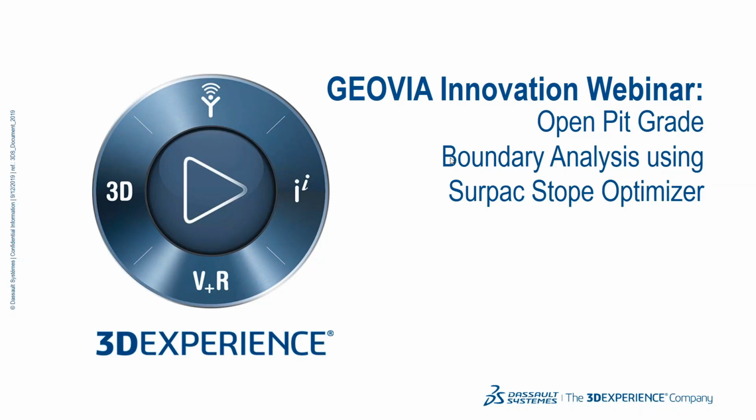One thing I should touch on that I didn't touch on earlier, the Stope Optimizer can be recorded in a macro. So all the forms that we walk through, all of those are saved into the macro, and you can certainly set up much more complex parameter settings. I just focused on simple grade cuts today. You could set up grouped variables to look at grade cutoffs, dilution skins, and so on.